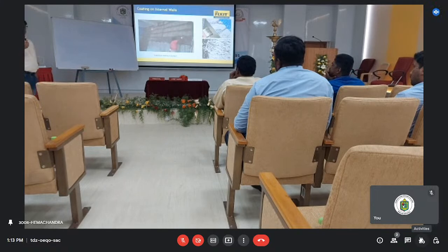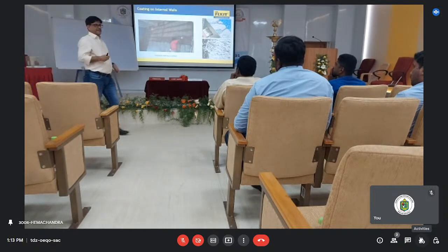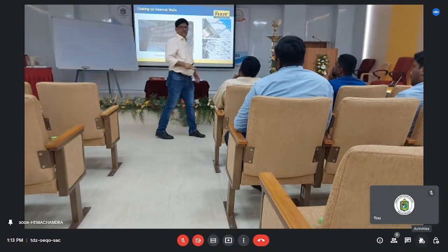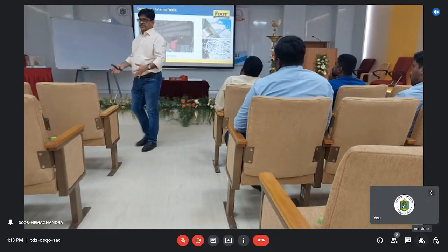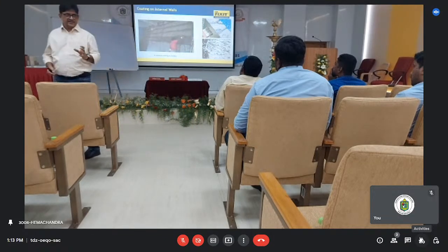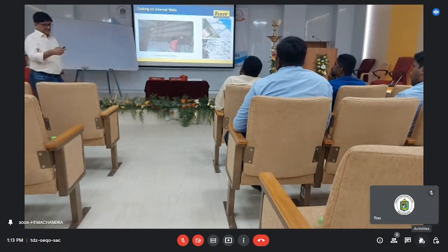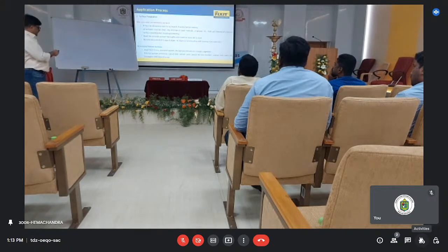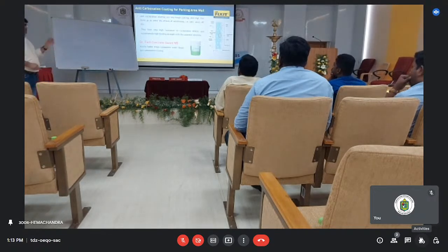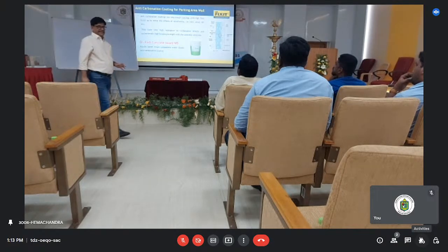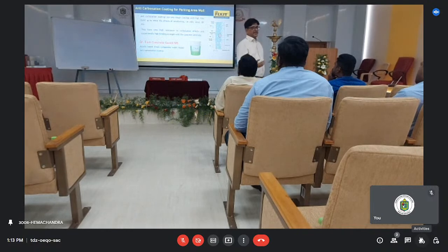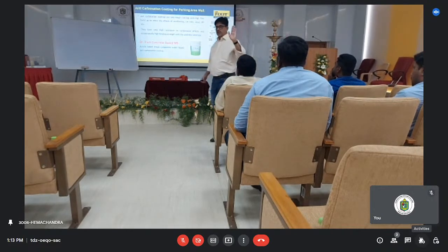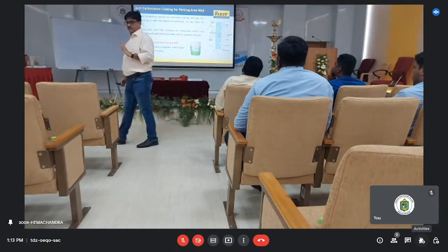So, the other area I told you about yesterday: another problem in basement areas is that, because of the vehicular emissions, all the columns and surface areas get carbonated very fast. Carbonation is one of the critical problems there. So in those areas, it is preferable to cover the concrete areas with an anti-carbonation coating. It's always better to take that protection. All the structural and concrete areas should get an anti-carbonation coating system.